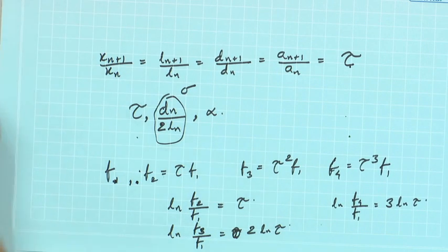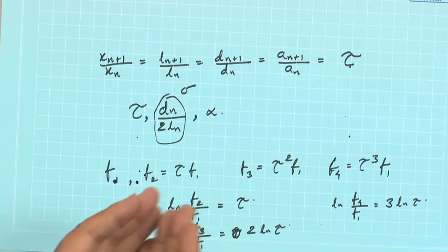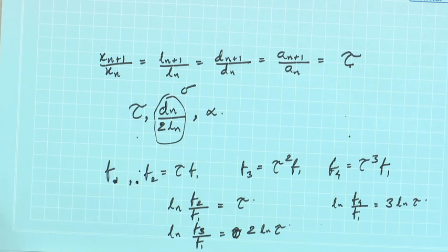It has also been found that at a given frequency, the currents in all elements except those that are close to lambda by 2 long are very small. That is obvious, because at a particular frequency only one structure is resonating.